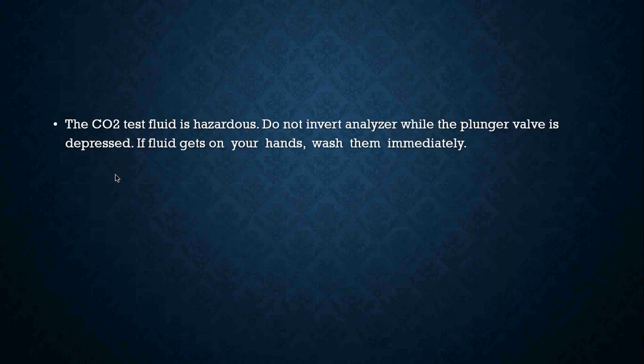One thing that is really important is the CO2 test fluid is hazardous. Do not invert analyzers with the plunger valve depressed. And if that fluid does get on your hands, you have to wash it off immediately. It can create a little bit of an acid burn on your hands. It can actually hurt. And that's it.